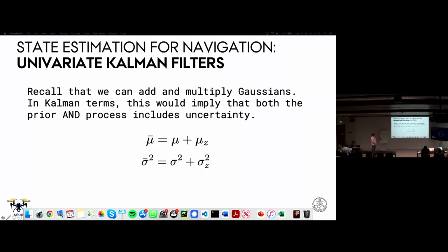This is quite powerful because we have a position, the current state that we are in, with an uncertainty associated with that position. So how did we get there? Are we certain, are we not certain? And then you conversely also have a measurement, which tells you that you are somewhere, right? A sensor giving you a measurement, and how much you trust that sensor is also encompassed into this standard deviation. And so this is why Kalman filters work so well.